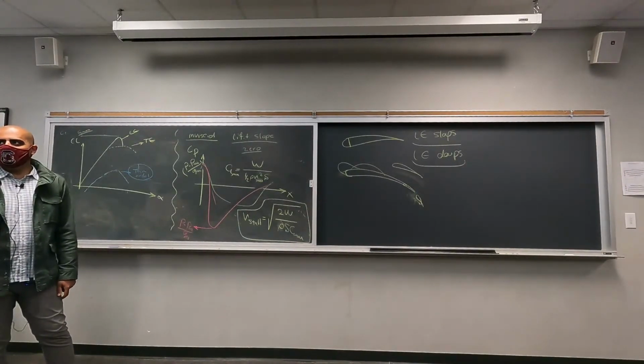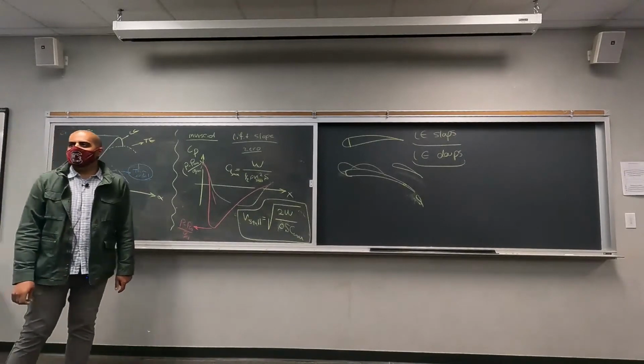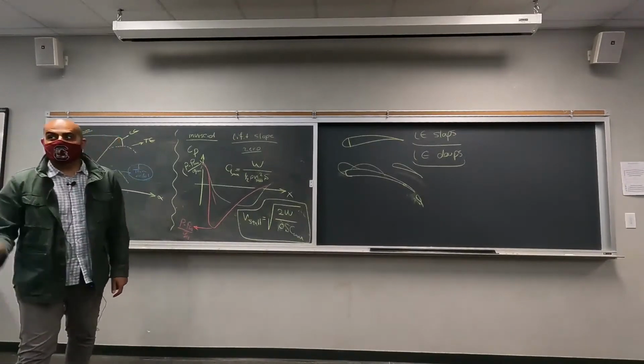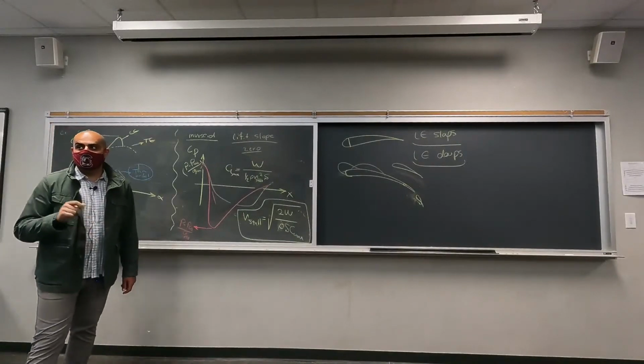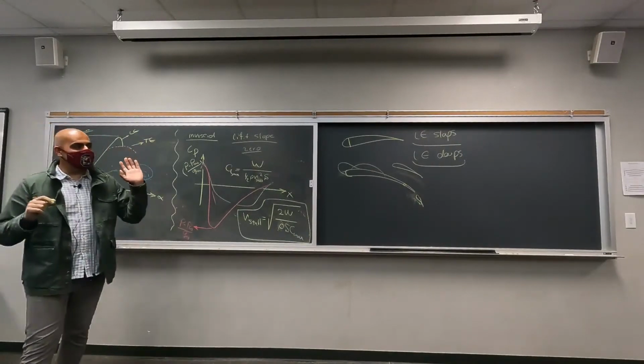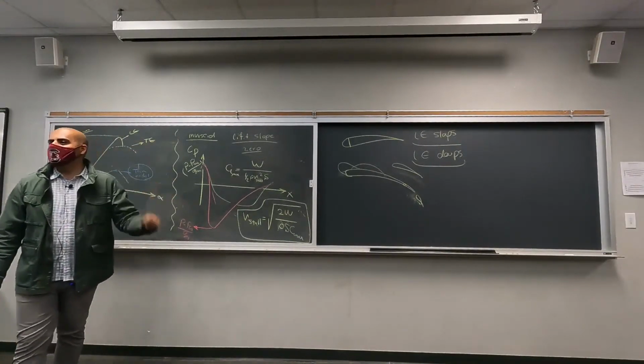I was thinking, you want to try to change the chord length, essentially. So if you had swept wings, do you actively change the sweep angle of your wings so you have a different chord length exposed to have your flow correction? That's for the 3-dimensional effects, right? We will talk about it later. What 2-dimensional changes can you make to an airfoil?